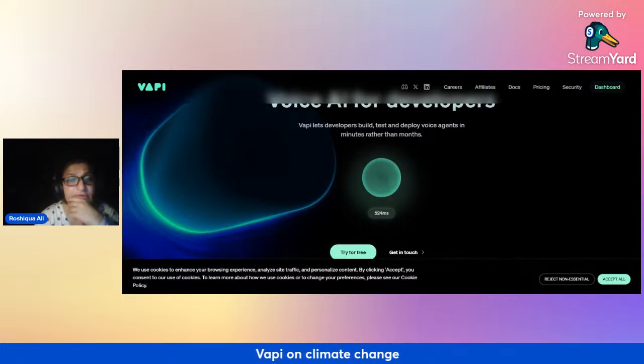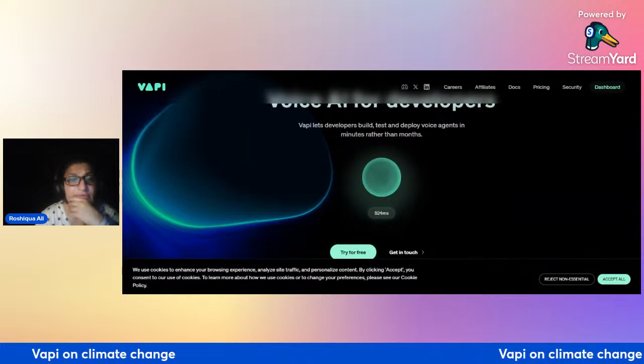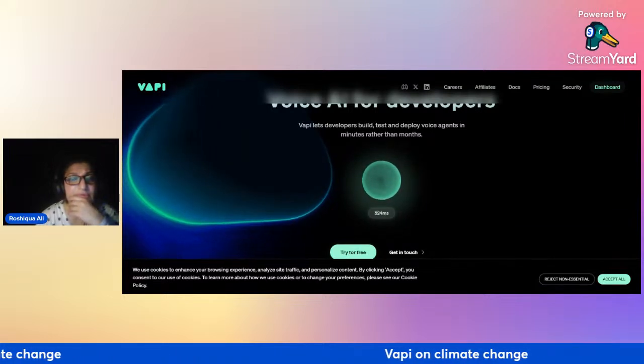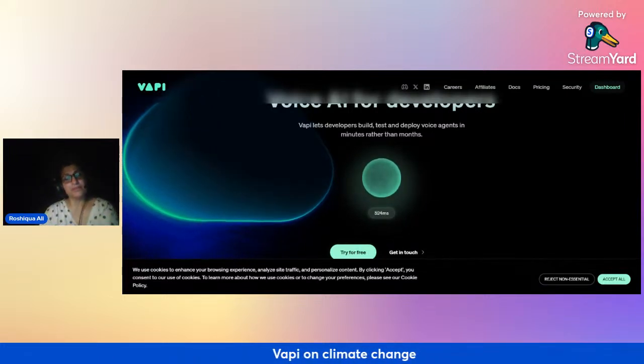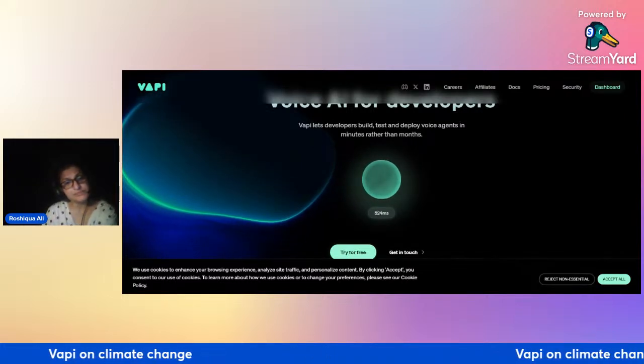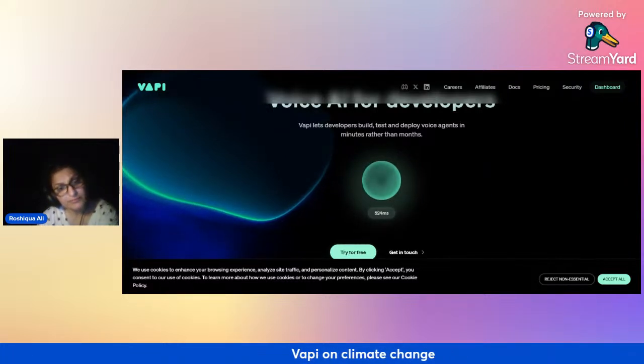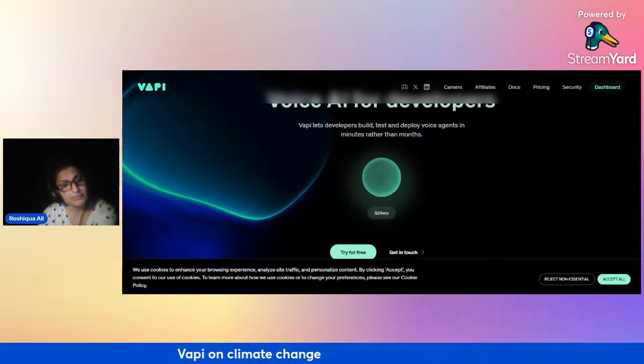Rammed earth is a construction technique where moistened earth is compacted in layers within a frame to create solid walls. The technique has been used for centuries and provides excellent thermal mass properties, making it ideal for hot, arid climates like those in Pakistan. It's like nature's own air conditioning system, keeping the interior cool and comfortable.